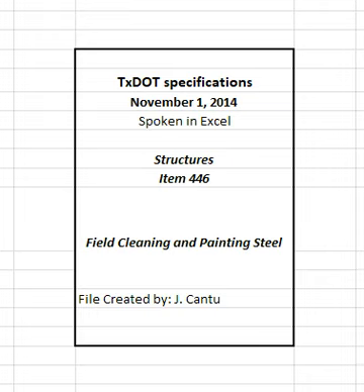Alternatively, liquids may be captured, stored, and characterized for disposal at an authorized facility in accordance with 30 TAC 315, pretreatment regulation for existing and new sources of pollution, or 30 TAC 335, industrial solid waste and municipal hazardous waste. Use a skimmer when cleaning and painting over bodies of water. Remove any blast or paint material the skimmer collects the day the release occurs. Correct the containment problem that allowed the release before continuing work.